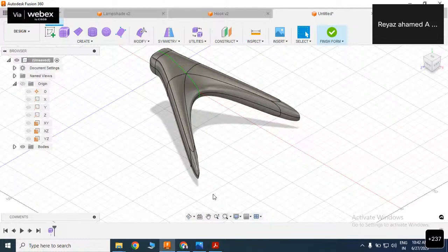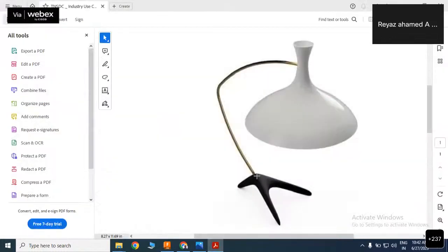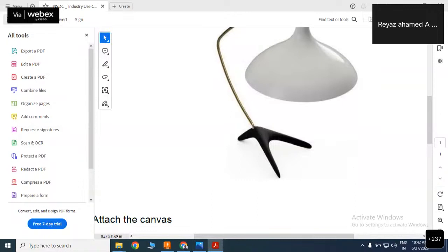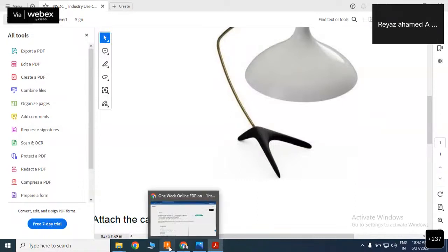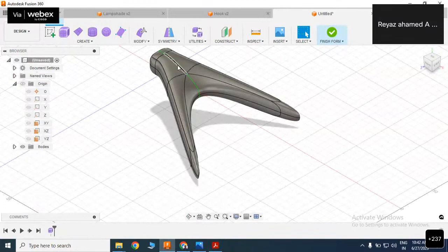So now some portion might be going towards upwards. Here there is a bend actually, right? So for that, let me move it somewhat based on this symmetric line. Click on this symmetric line, the green color line. Double click on this. It is not fully selected, only partially selected. So with the help of the control key, double click on both the sides.